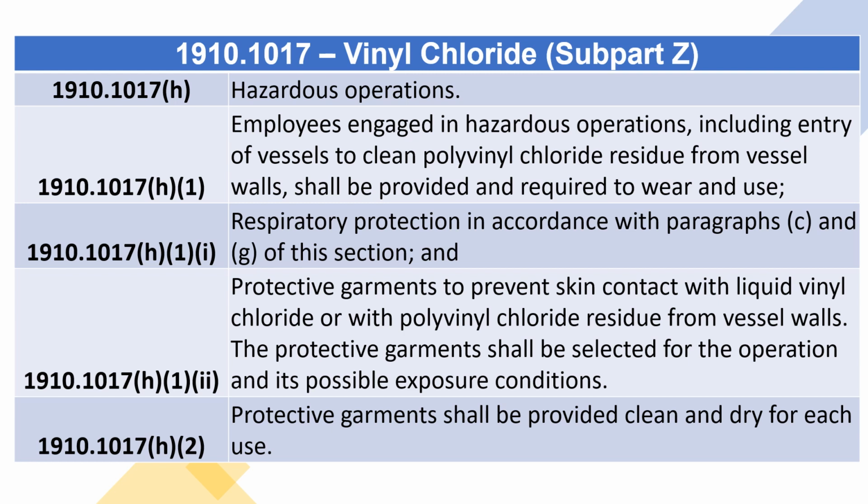1910.1017(h)(1)(ii). Protective garments to prevent skin contact with liquid vinyl chloride or with polyvinyl chloride residue from vessel walls. The protective garments shall be selected for the operation and its possible exposure conditions. 1910.1017(h)(2). Protective garments shall be provided clean and dry for each use.